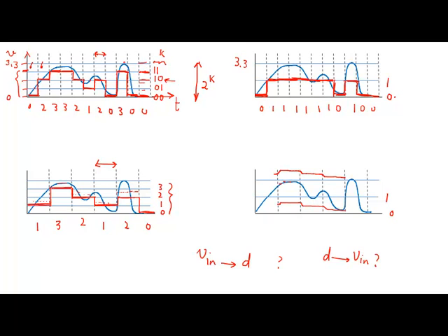One is the electric characterizations of your sensor and also your PIC microcontroller, because the way that A2D devices work is that you load charges on a capacitance inside your A2D device so that its voltage becomes equal to the voltage of the input, the sensor, the input value that you have, right? And it takes time through an RC circuit for that capacitor to charge up. That's called the sampling time.